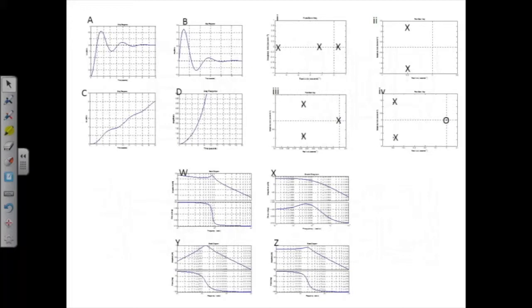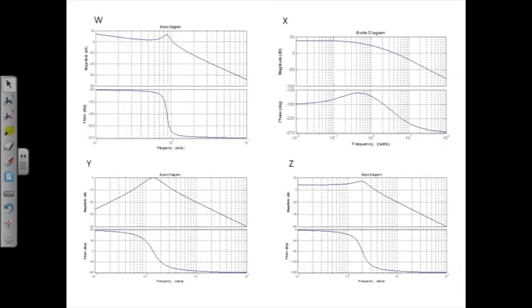So is your maximum phase shift going to be 90 degrees on a stable system? No. The phase information from a pole in the right hand side carries a minus sign with it. So what would have been a positive real pole if it was on the negative side, we start off with 0. But because that first order pole is on the right hand side, we're starting off effectively with a minus sign, so it's minus 180. So that's why it starts at minus 180.